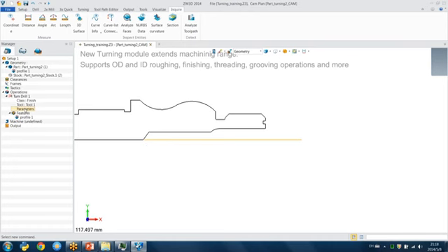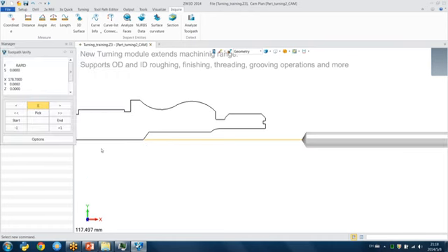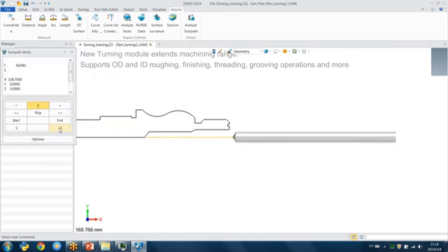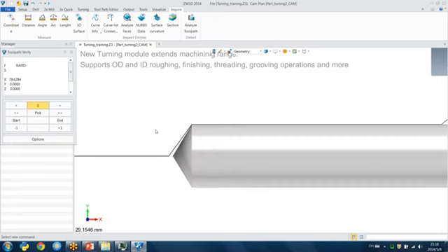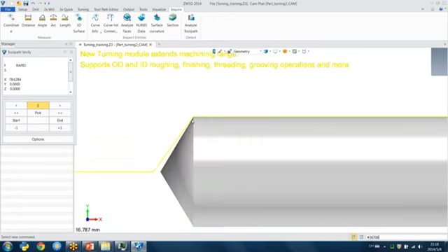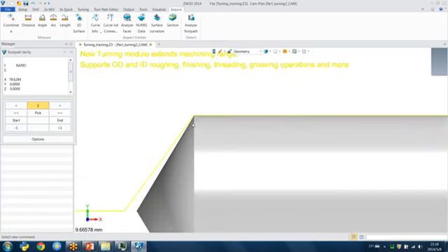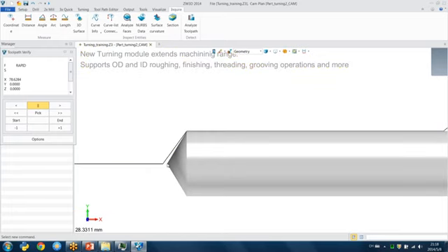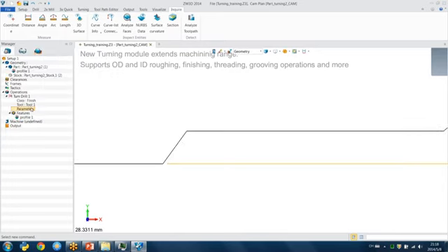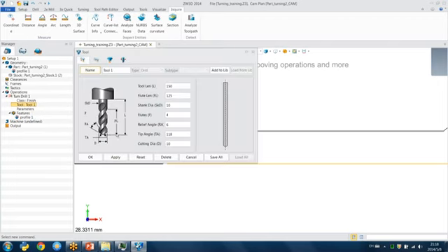Okay, this is the gel. So let's see in the verifier, and you can find why the tools cannot get much more inside, because this one is locked. If you want to do the same, you must modify the tools. Okay, so I need to edit the tools. Right click and edit the tools angle.